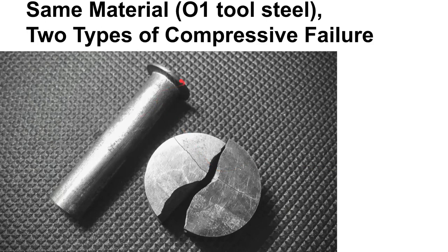All right, so another look here: a nice tough material, but not as strong. A stronger, higher tensile strength material, or compressive strength in this case, but not nearly as much plastic deformation, not nearly as much ductility. So we might say this is tough and this is brittle.